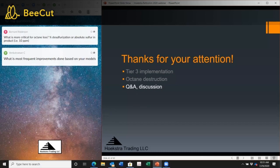The FCC feed pretreat, or cat feed hydrotreater, I think is the key for making the manufacture of 10 ppm sulfur gasoline consistent, reliable, and profitable. And it's the refineries that rely strictly on the post-treater, the gasoline desulfurizer, to do the whole job. That is the difficulty that we have in the US.